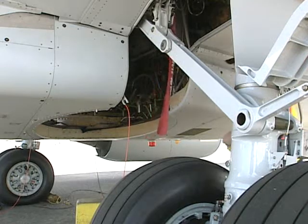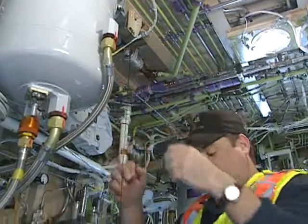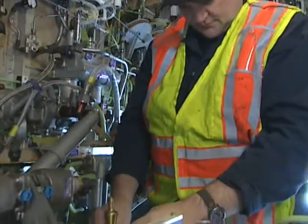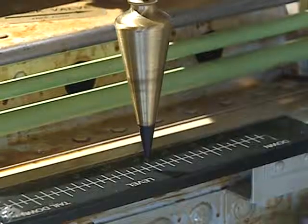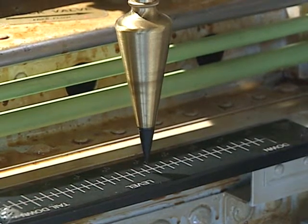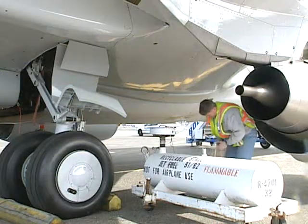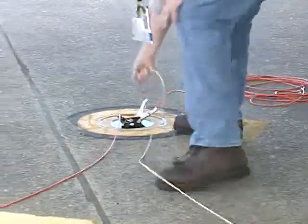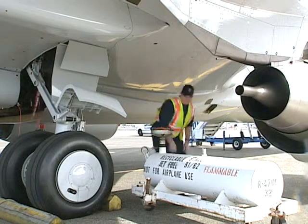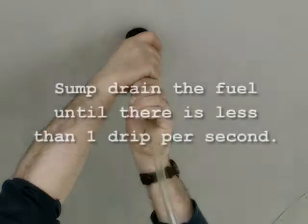Now, make sure the airplane is level to the specifications for defueling provided in the maintenance manual. Note that the airplane pitch attitude for defueling may not be 0 degrees. Then attach fuel drains to the sump drain fittings. Allow the fuel to drain until there is less than 1 drip per second.